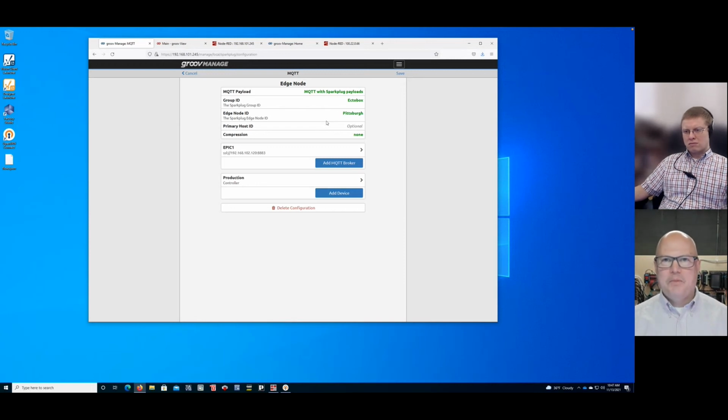The drawback to MQTT is that you can publish to any topic. So this puts a little bit of some rules and configuration on, what is my device? This is the payload. This is what you can expect, so that I can actually use the Sparkplug B to do control. I can actuate and turn things on and off using that Sparkplug payload.